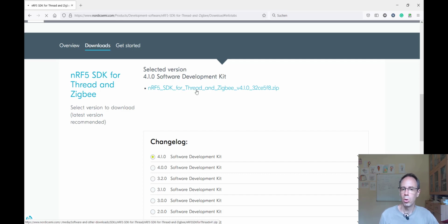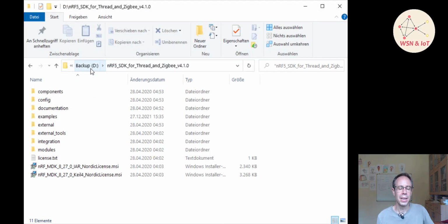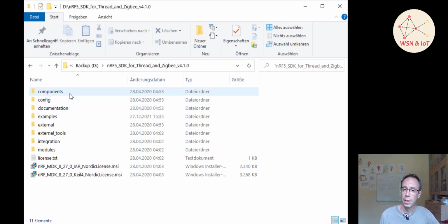But when you extract the folder, make sure you don't put it too deep, don't place it on the desktop or something. Make it near to the root folder. Make sure the path names don't become too long. This can cause compiler errors later. Also avoid white spaces.